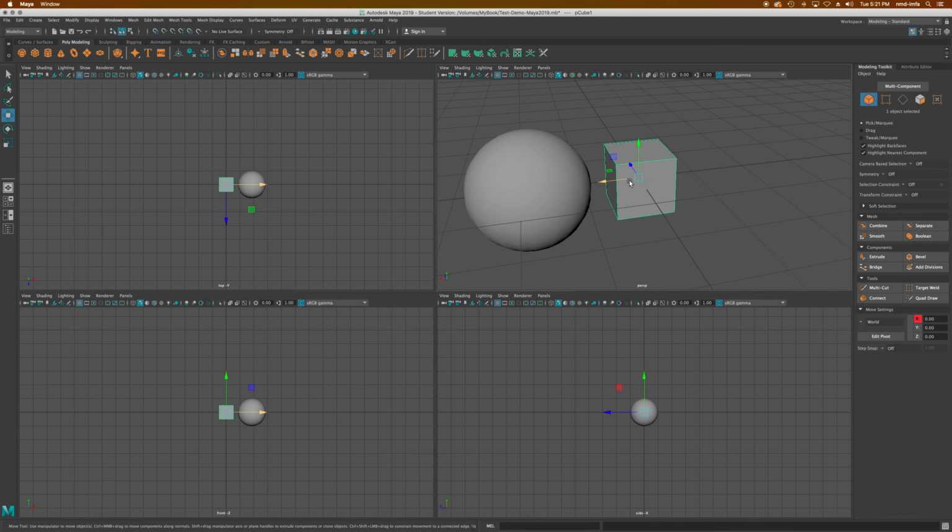But it allows you to basically select, if I click on the little square in the middle, it's just going to move the cube around kind of willy-nilly in all dimensions. If you look at my other windows, you'll see I'm moving it left, right, up, down, kind of all over the place, right? I'm going to go ahead and undo. But if I choose just the red dimension, then I'm going to move just on the X plane. So I'm just moving in the X direction as far as X, Y, and Z goes, right?